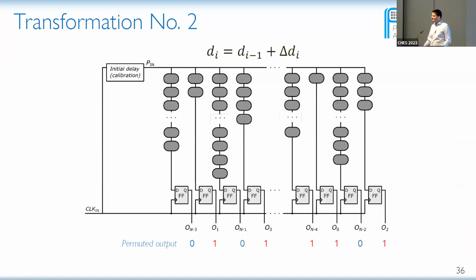I completely understood the concept, but what I'm not getting is this is encoding, let's say, a variant of power consumption. In the TDC sensor, you have a very nice transition from 1 to 0, and you can encode or decode this to something else and say this is a value that you have. But here, there are some bits that don't have any particular order because the placer and router just decided to route them like that. How do you know that some bits are not very close to each other, and there is some gap between the delay of one line to another one, and you are missing something? And how do you actually convert this to real power values, to show that this is the power value compared to TDC?